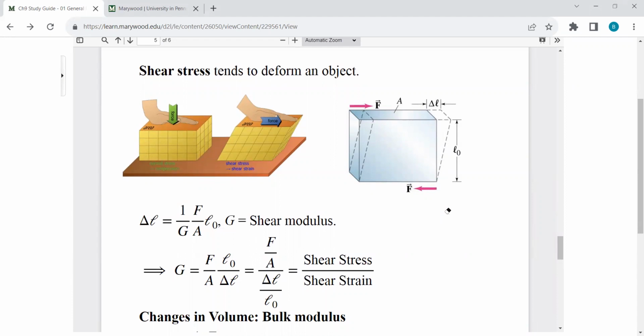So what is shear stress? To understand shear stress, let's say we have an object something like this. Now if you push it downward, it will be under compressional stress. But instead, if you apply force like in this picture, you see that the shape of the object changed. The object deformed from its original shape. If we have something like this, we call the object under shear stress.